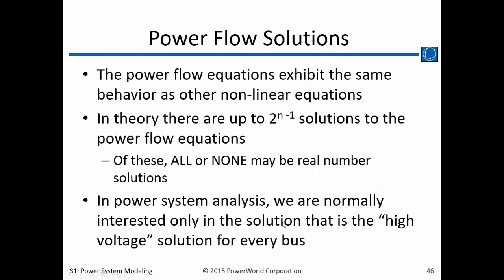The power flow equations exhibit the same behavior as other nonlinear equations. In theory, there are up to 2 to the n-1 solutions to the power flow equations. Of these, all or none may be real number solutions. In power system analysis, we're normally interested only in what we call the high voltage solution for every bus.